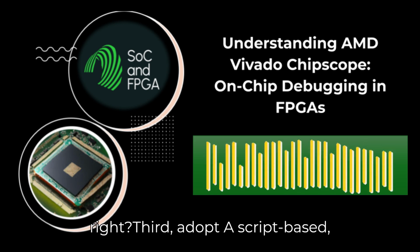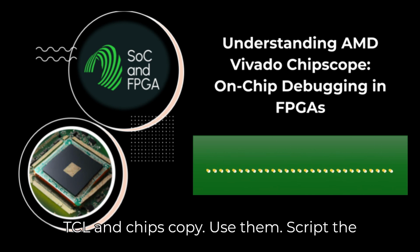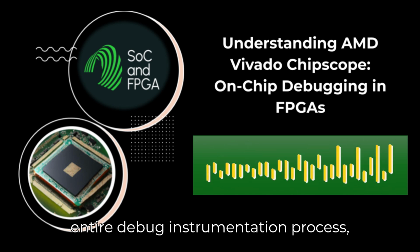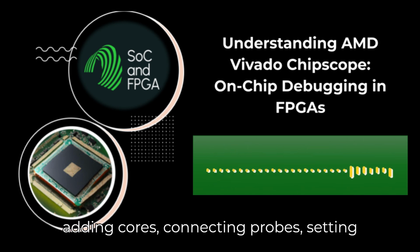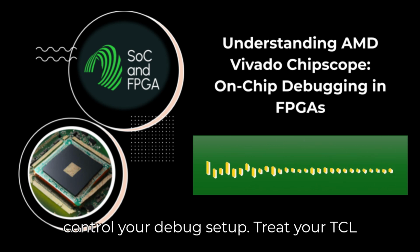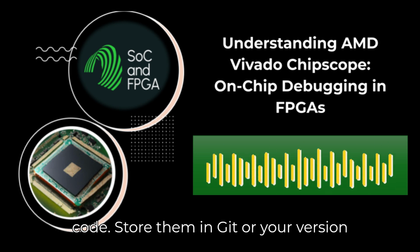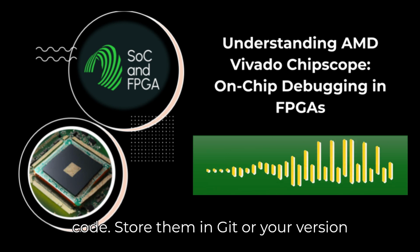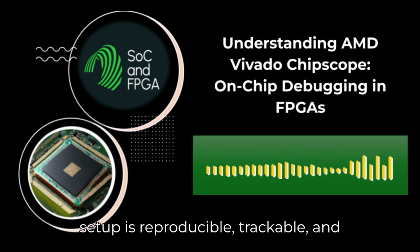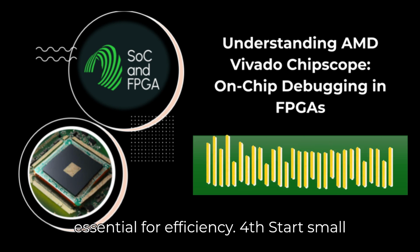Right. Third, adopt a script-based, reproducible workflow. We talked about TCL and Chipscope. Use them. Script the entire debug instrumentation process, adding cores, connecting probes, setting parameters, and absolutely version control your debug setup. Treat your TCL or Python debug scripts just like source code. Store them in Git or your version control system. This ensures your debug setup is reproducible, trackable, and easily shareable with colleagues. Infrastructure for debugging. It's essential for efficiency.